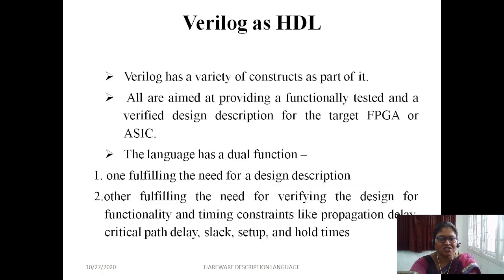Verilog HDL has a variety of constructs as a part of it. All are aimed at providing a functionally tested and verified design description for the target FPGA, that is field programmable gate array, or ASIC, that is application specific integrated circuit. So the language has two functions. One, fulfill the need for the design description. The other, fulfill the need of verifying the design for its functionality as well as timing constraints like propagation delay, critical path delay, slack, setup and hold time.